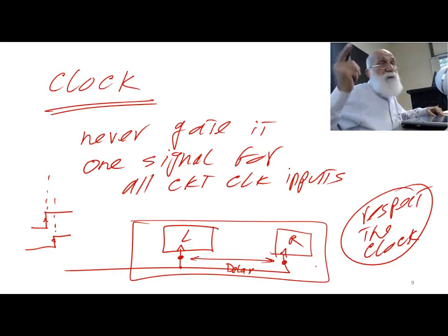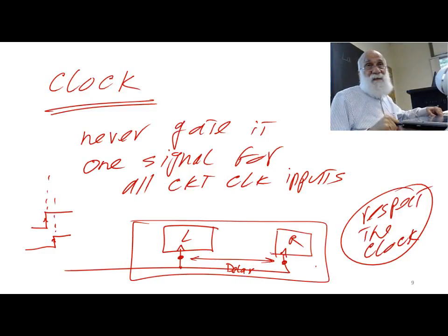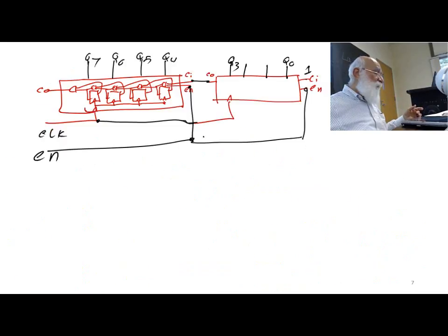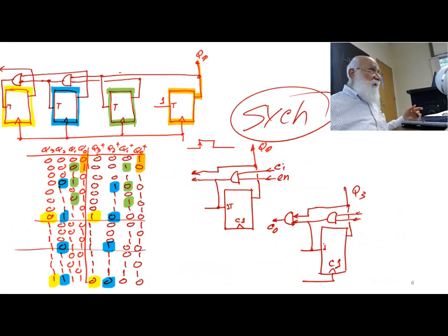When we are doing a clocked circuit, we don't play with the clock, we don't let the clock participate in the design either. What it means is that when I want to do a counter like this one, for example, I bring the clock, connect it to all my flip-flops, and say, now, let's start from this point on.